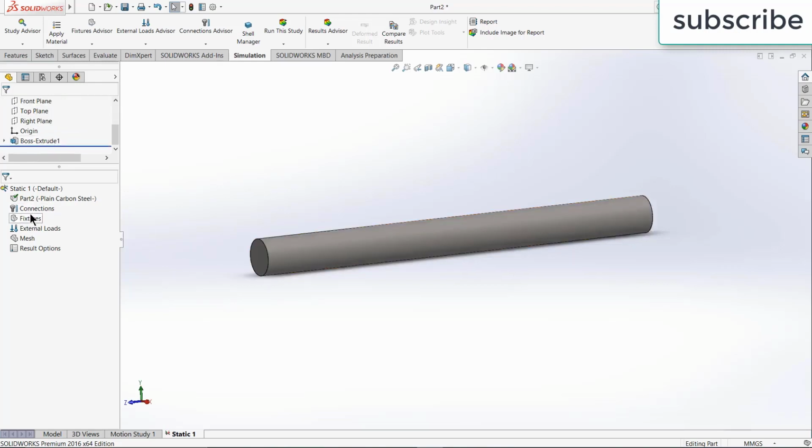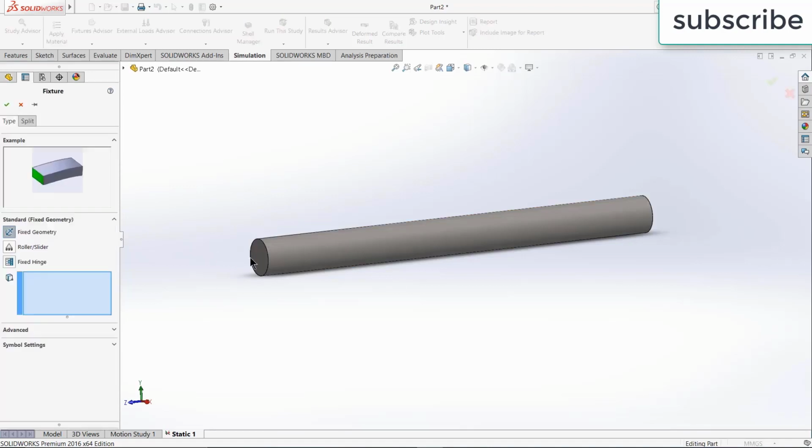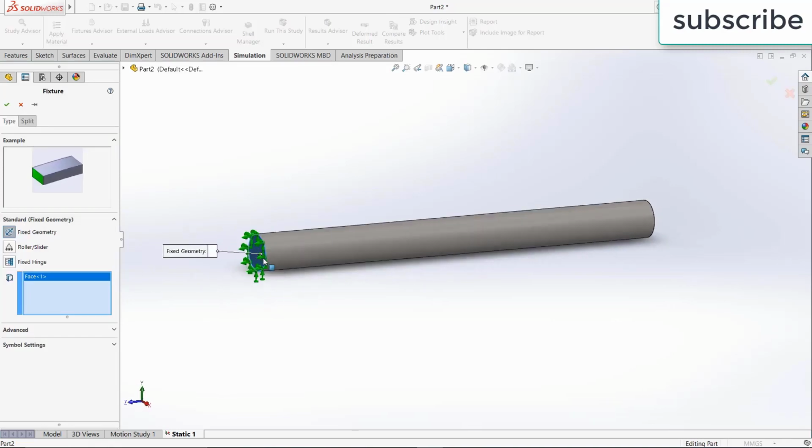Okay, so here is the fixtures. Fixture basically means what you want to fix or move. So right click on fixtures, click on fixed geometry, select this face. So basically, this face is fixed. This face is not going to move. This is what it means by fixed geometry.